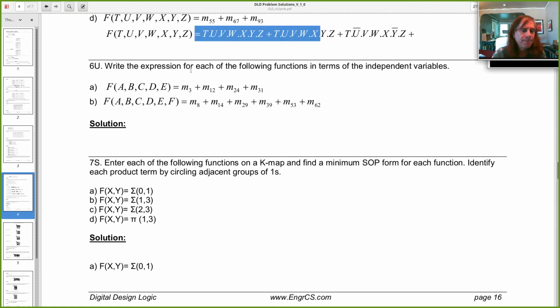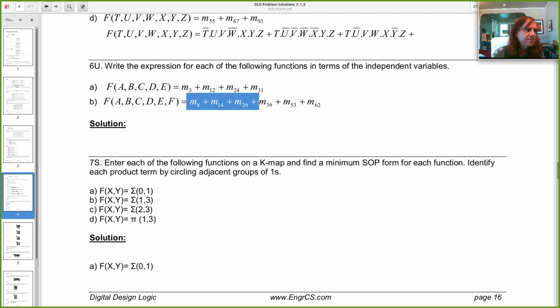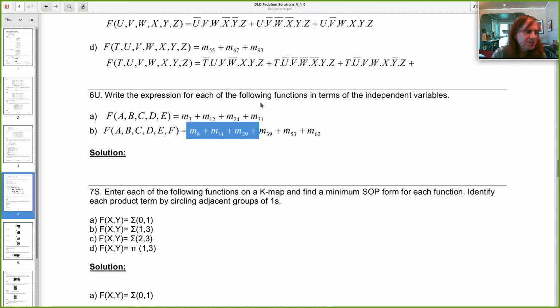So you're wanting us to simplify? Not so much simplify, but convert from this kind of expression to that kind of expression, a sum of products where you're actually listing the individual inputs and their complemented values. But you can do that translation without having to go through a 64-row truth table in this case. You can just find the binary number. Yeah, basically. And then that'll tell you what the input should be, right? Right. But if that doesn't make sense to you, discover it.